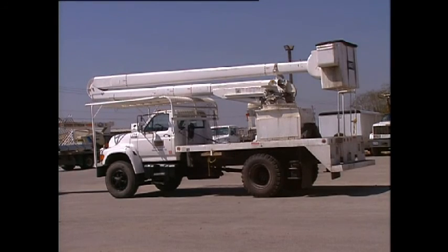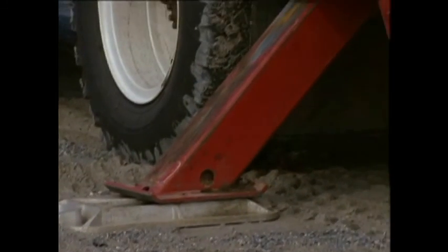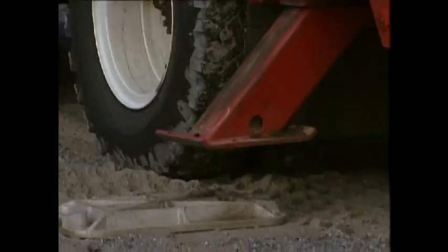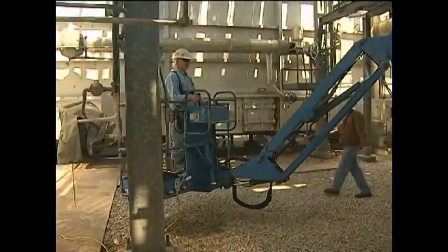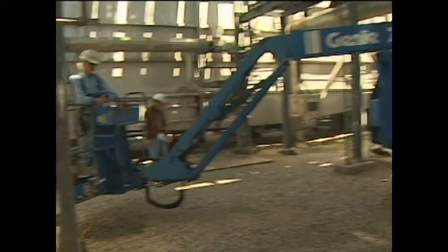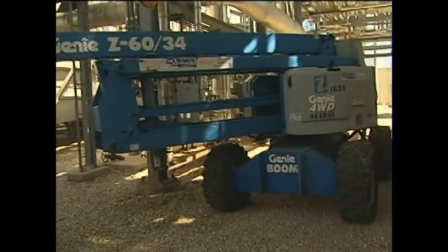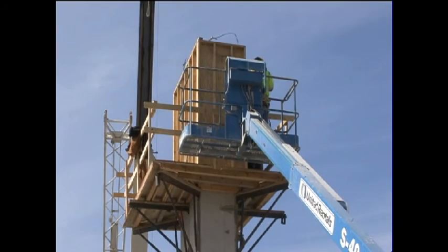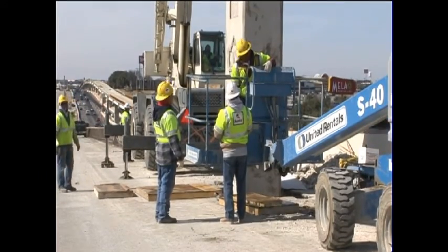Before moving, the boom must be properly cradled and outriggers must be stowed in position. A person on the ground familiar with the lift should guide the operator when transporting the lift from one area to another on the work site. The operator must make sure that the boom is never over an individual that is on the ground.